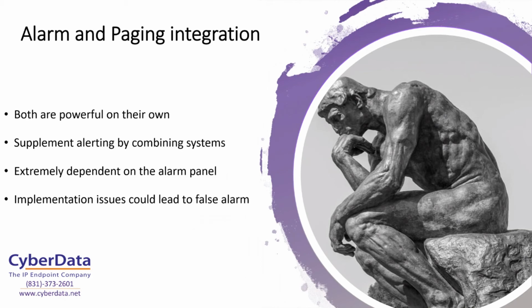But one of the main downsides that a lot of places will encounter when they try to go for things like this is the capabilities are really dependent on that particular fire alarm panel. If they've got an older fire alarm system, maybe installed in the mid 2000s, it might not be as advanced as they would like. It might not have an onboard amplifier. It might not have a capability to actually take in line-in audio to play it through its horns, or the different ways that it can make announcements. Or maybe it just can't even do any of that.